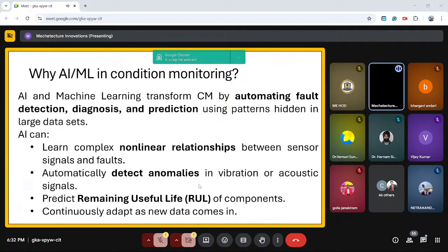Say a machine can run at various conditions, so the signal is also affected by the conditions. If you are working under any kind of conditions, your data will be affected, right? So that data also has to be taken into account. I cannot simply say a particular value of the sine wave is the limit, because that depends on the condition in which I am operating the machine. So the limit varies with the condition at which my machine is being operated.